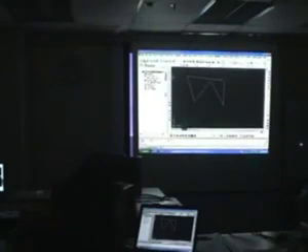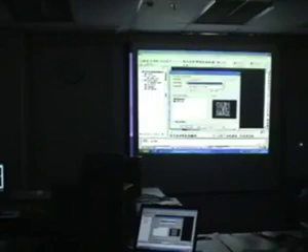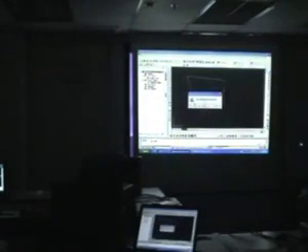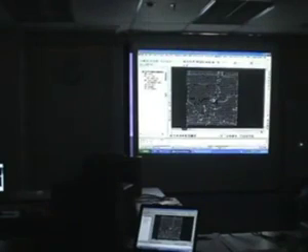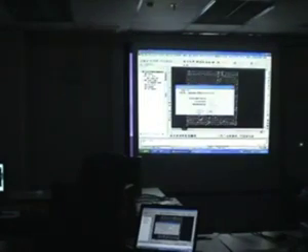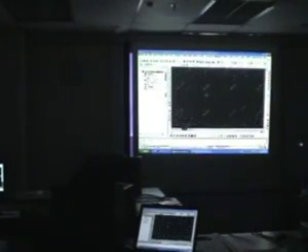For this you can see how it works. So I'm just going to open. Okay, this is my project. I'm going to open 2D points. This drawing, 2D points.dwg, is actually a file which only has text that's supposed to indicate the spot levels. I'm just going to zoom in so you can have a look. So these are all the different texts which indicate the 3D levels of each spot height.